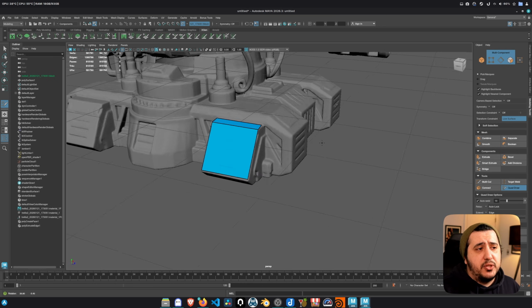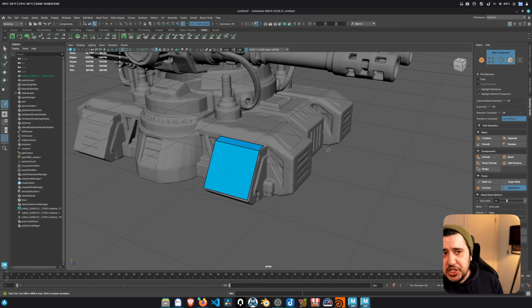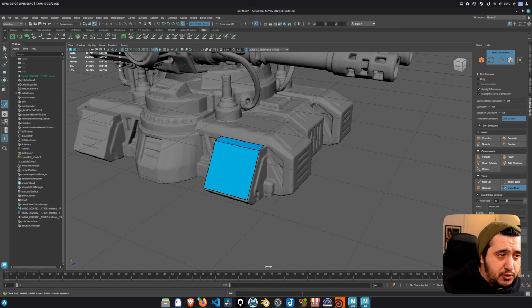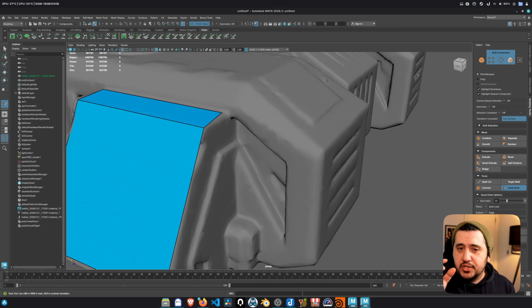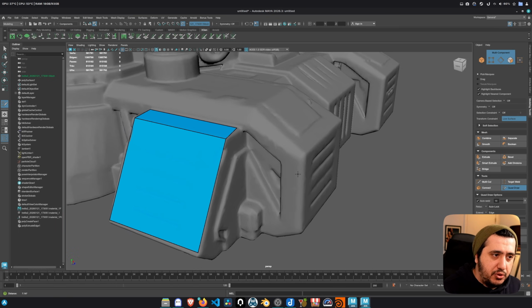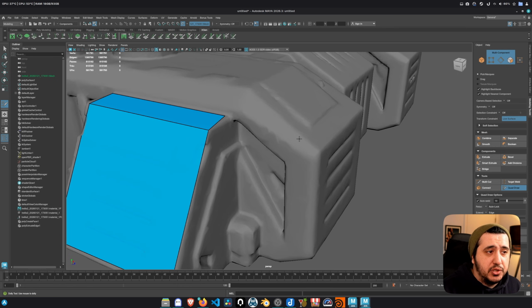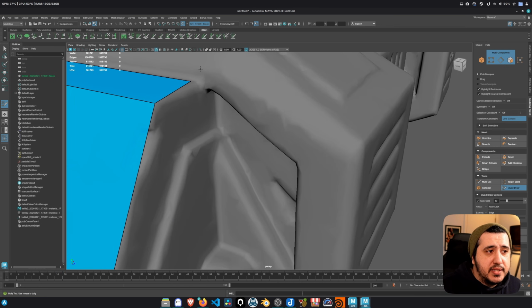What is the reason for doing retopology? Optimization and also getting a better looking result. So this is a hard surface object and we want to see those nice sharp edges. As you can see, we don't have them because of the pixelation, triangulation. We see these weird shading artifacts that we call.